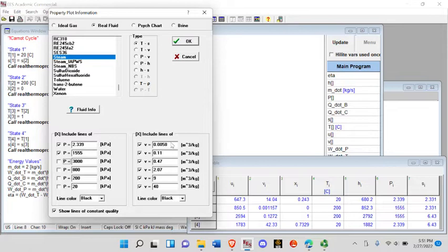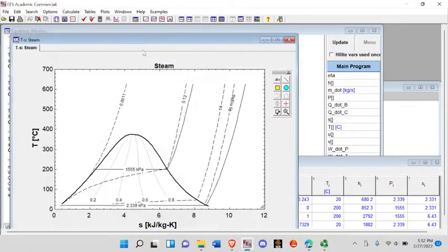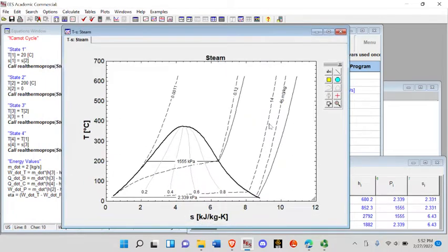Include specific volume. So I'll do 14.04. Oops, 04. Then we have 0.001157, 0.1272, and 42.33. Gonna uncheck these boxes. You can change the line color. We're gonna keep them. And again, we found the specific values here from our array table. Gonna hit OK.